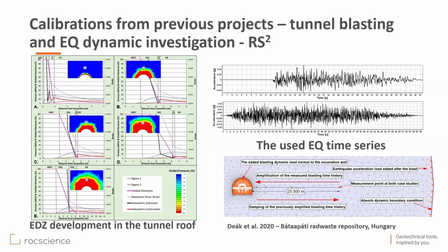So firstly, we had here the measurement point, and from here we made an amplification for the blasting time history, and then we loaded the tunnel wall, and then using Rayleigh damping of the previously amplified blasting time history, we rechecked the results, and you can see the final results, how it looks like.